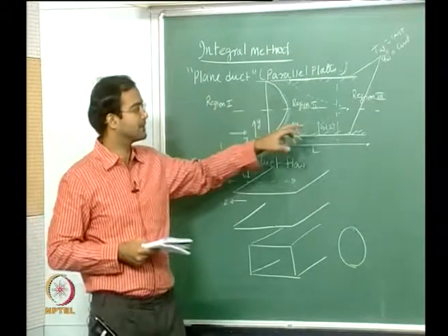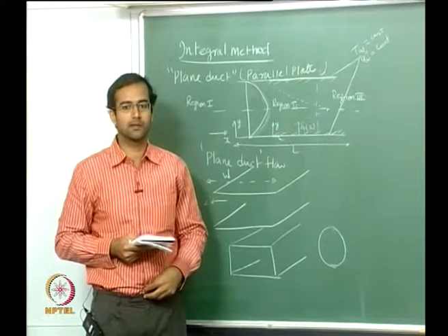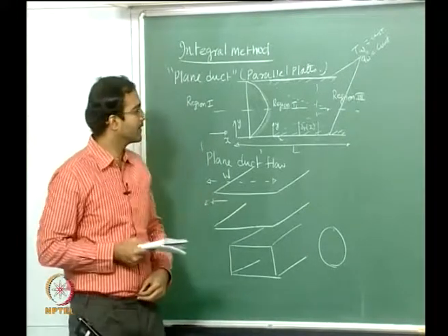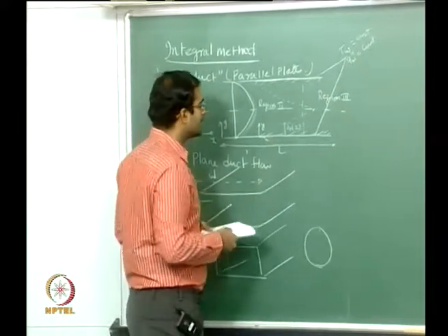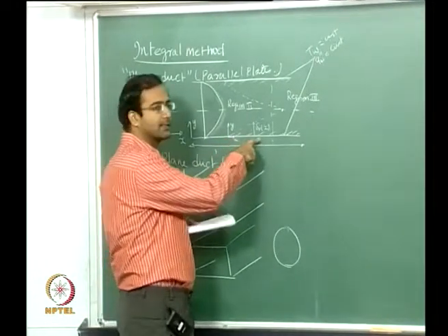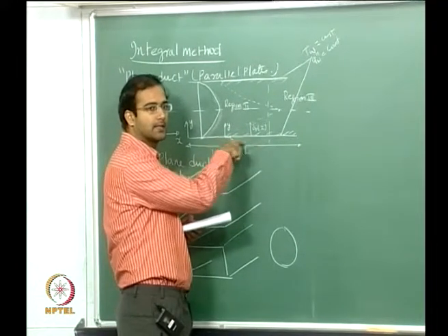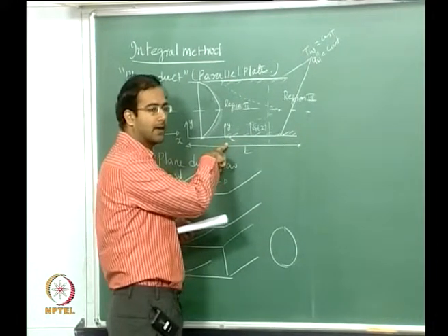Once the viscous effects start coming, the definition of your actual boundary layer approximation will not be valid. So clearly, within region 2 it can be applied from the start of the boundary layer to a certain distance downstream. These momentum and energy integral approximations can be valid there.